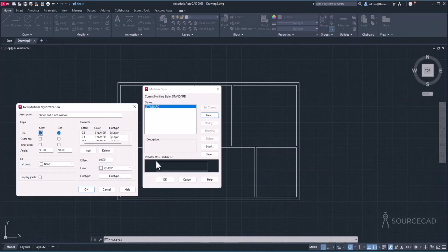The angle here for this is 90 degrees, and for the ending line also it is 90 degrees. If you want to incline it, well, you can choose the angle. I don't think inclination is required for this line, but if you want, you can type like, let's say 60, and here it is. Now it is inclined to 60 degrees. So I'll just change it back to 90. I want it perfectly vertical.